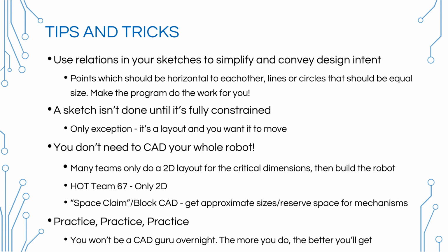The only exception to that is if you're using a layout sketch to figure out the kinematics of your robot. And so you want this arm to move along an arc or something, and then you leave it undefined in that degree of freedom so that you can click and drag with your mouse and make that arm move where you want it to go.